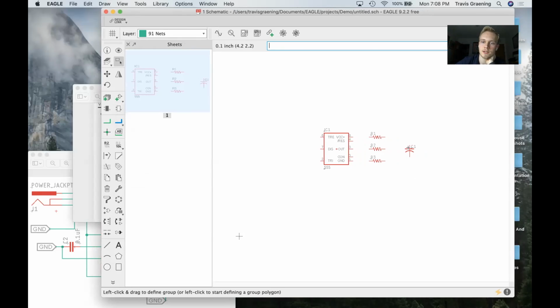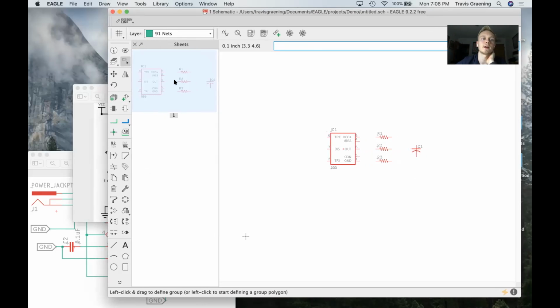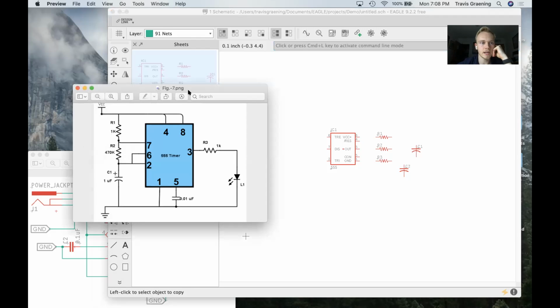Okay, so I'm just going to pick 2 capacitors with the same footprint right now, although technically our electrolytic one might have a slightly different footprint than our regular nonpolar one. So I'm just going to use our copy function actually right here, which is another one we might not have talked about so much. Just click on this component, and then you can see we've made a second one. And we can just move this down a little bit, and it names it capacitor number 2. So there we go. We've gotten most of our parts already.